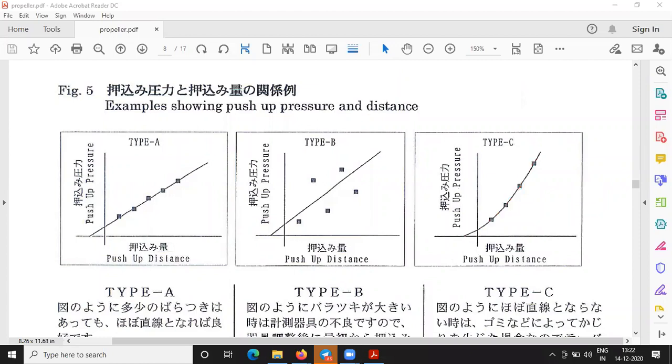Next, see how the apparatus may go wrong. There is a hydraulic pump. For every stroke, it has to pump in 50 grams of oil. But because of loose o-rings or anything, for one push-up it gives 50 grams of oil, next it gives 45 grams of oil. So what happens? An irregularity is created in these strokes, and those strokes will cause irregularity in the push-up distance also. Finding my point?